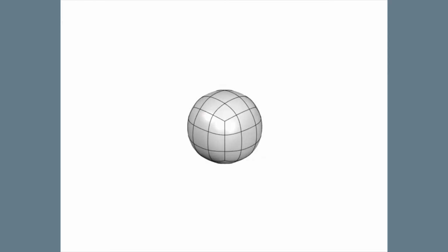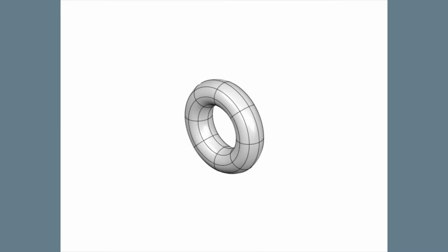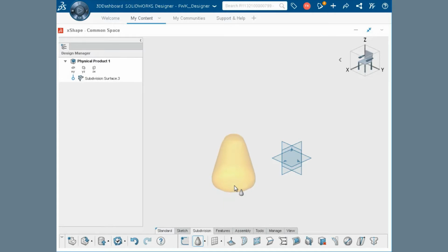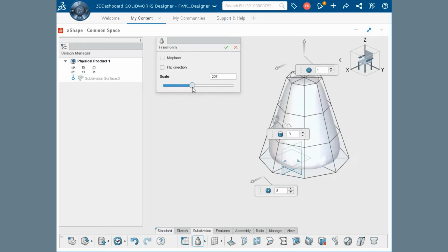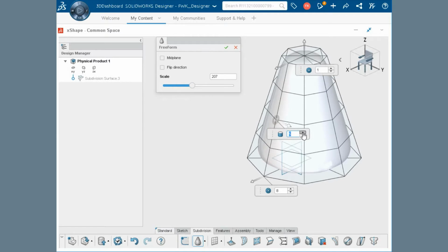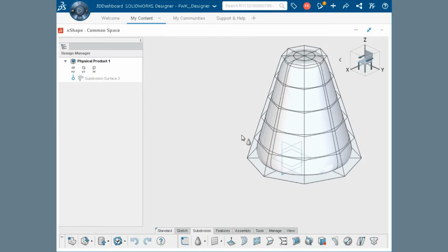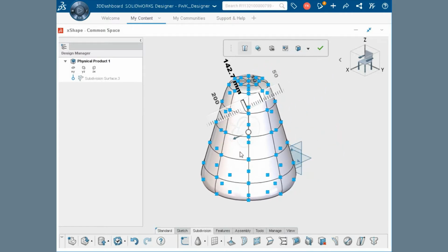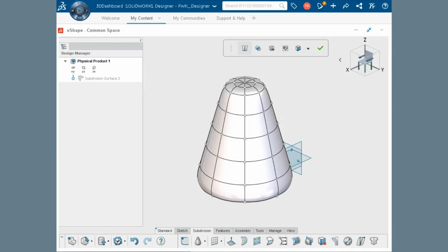Note that you can create multiple primitive surfaces and, with the additional tools and power of XShape, combine them to finalize your model. While adding a primitive sub-D surface body, you can adjust the orientation, number of loops, scale, and position in space of each as you create it. Some of these shapes, like the cylinder and cone, have a drag handle to set the rotational section in degrees.